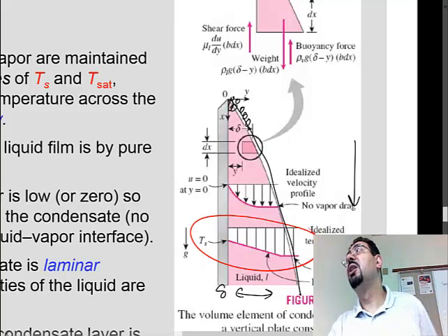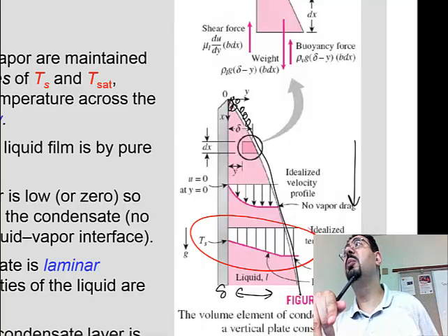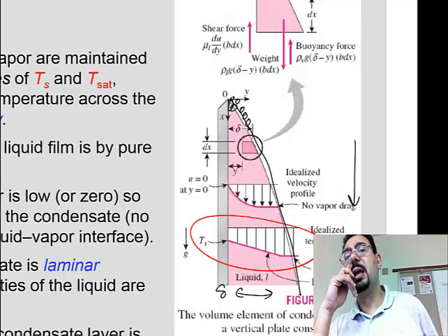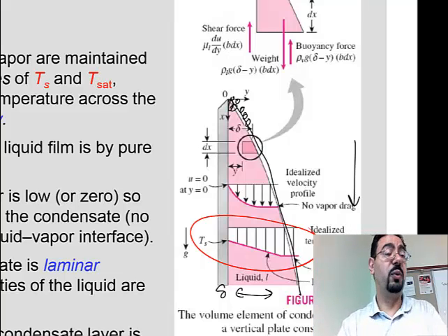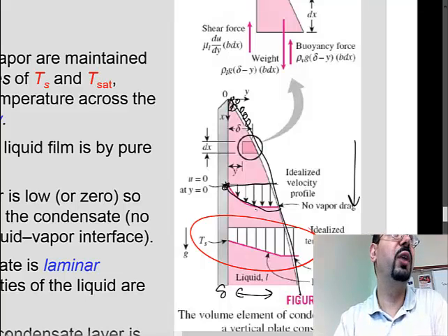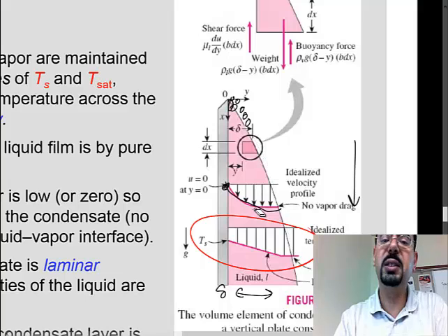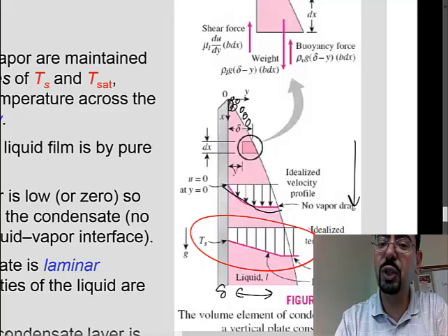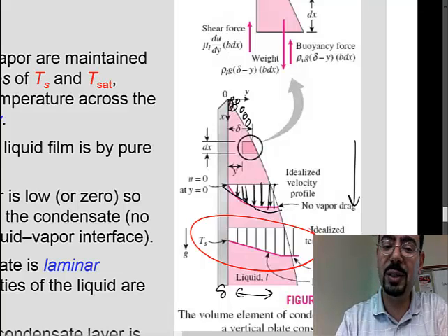The pressure? No, everything is atmospheric over here, by the way. Friction. The water droplets slow down as they get to the bottom. So there is a velocity profile, and that velocity profile is like this, because this wall is not moving, and the fluid next to it needs to be the same velocity as the wall. But that's not the reason why it's getting bigger. So yes, Jesse is right, there is a velocity profile, but that doesn't explain why the thickness is getting bigger.